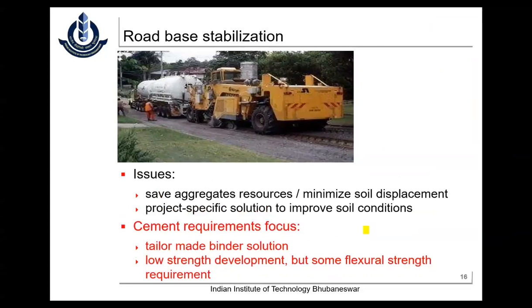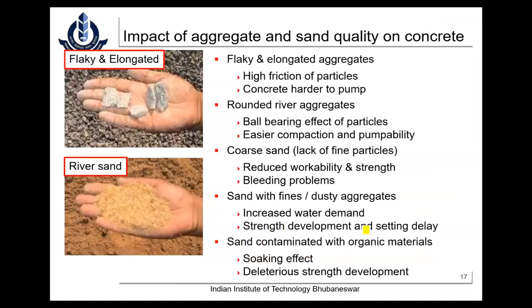Also, as I already mentioned initially, though your cement is good, if the other raw materials are really bad, ultimately the final product will be affected. Ensure that the other materials, the aggregates or the sand which you are using or the admixtures, are adequately of good quality so that ultimately your recipe will be good. That is what I emphasize everywhere actually.